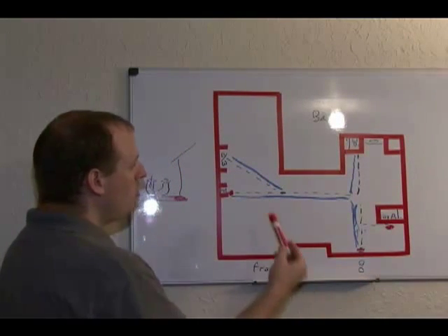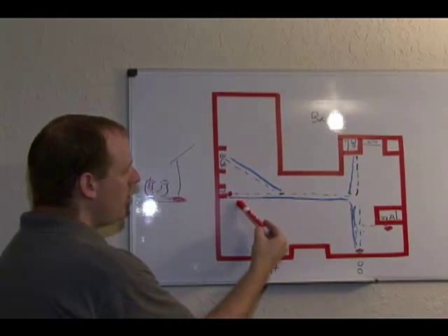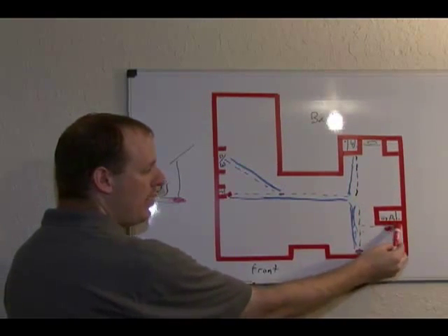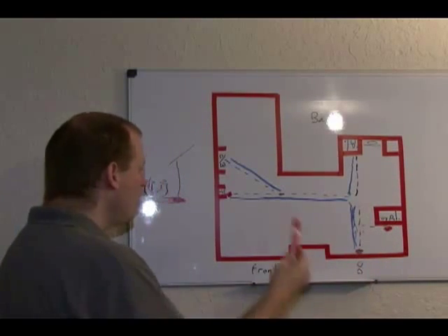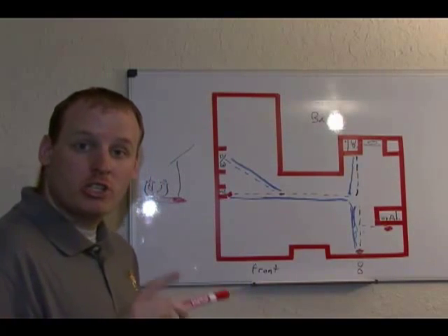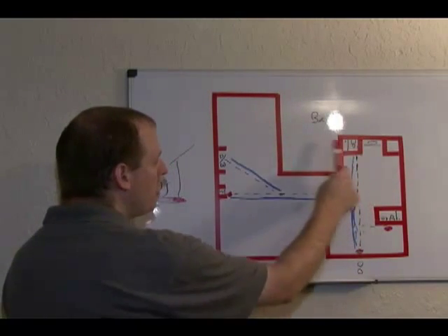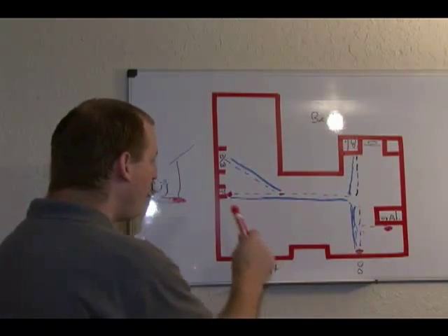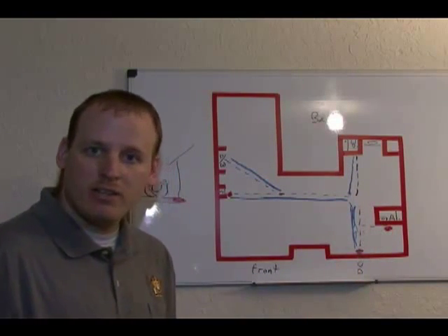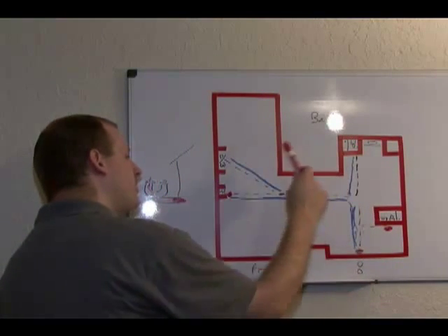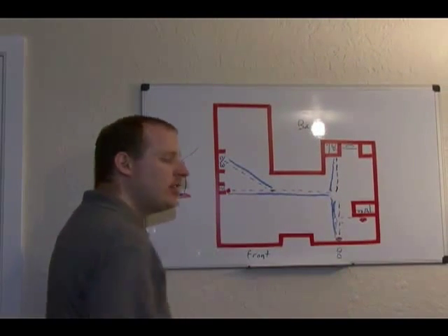At that point, we would again test everything except for this bathroom, which would be blocked off, and this kitchen, okay, which is blocked off. We would be able to test everything. At that point, it would show no leaks because we found our 2 leaks that we said we had, okay, and we would say that nothing leaks except for the kitchen and the bathroom.